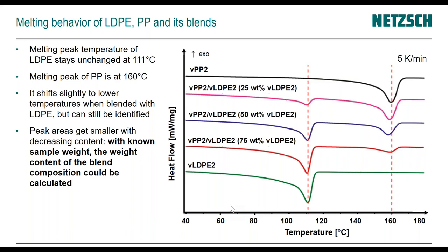And then there's the question if there's any database with the characteristics of the main plastics, glass transition temperature, crystallization temperature. There definitely are different databases that you can purchase that search through data sheets from material suppliers and offer a compilation of that. If you Google, you'll probably find MatWeb and others.